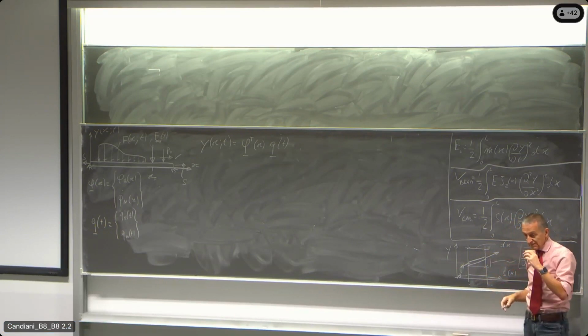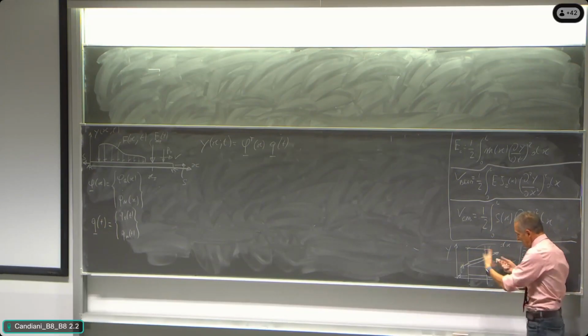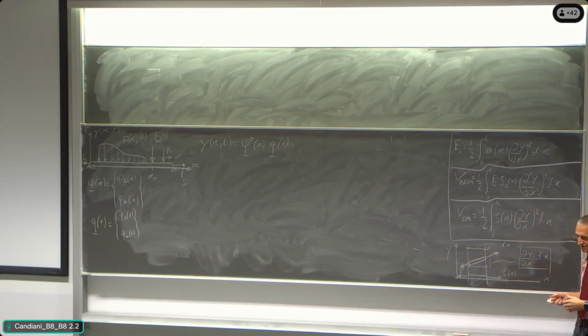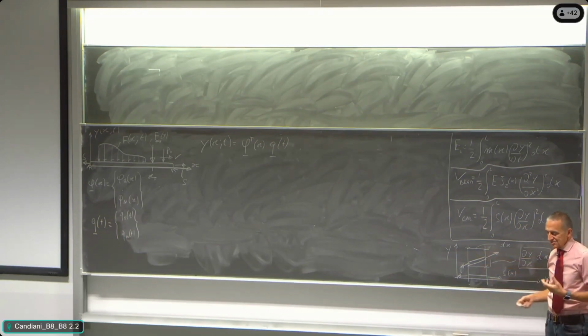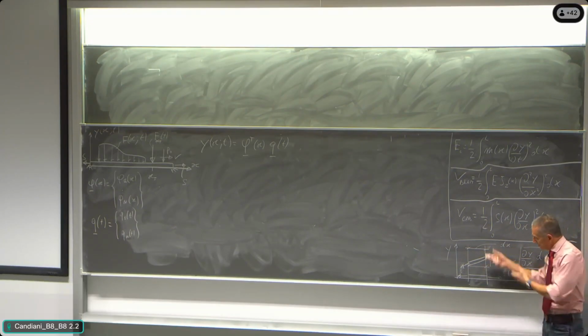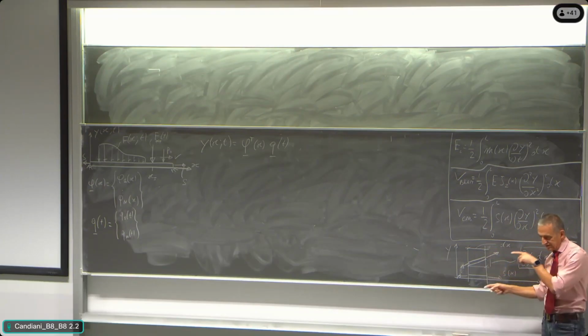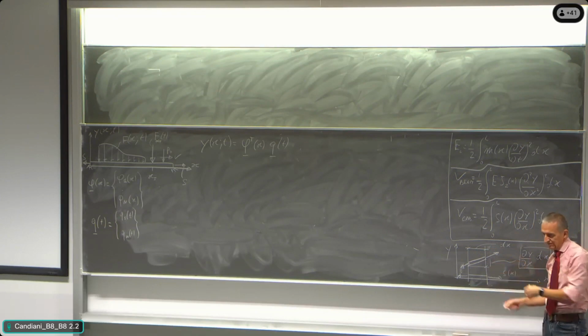So there is a contradiction there. The contradiction is that also applying this theory now, we are saying that the tension S could be a function of the location x, but is not a function of the displacement y. So this is a contradiction because we are saying it is moving away from the straight line, it is inclined, it is longer, and we are writing how much is longer, and so it has more potential energy.